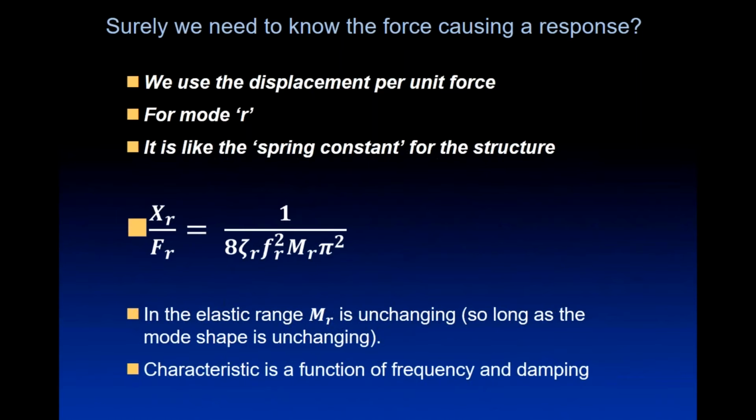Next question, though, is what about damping? Now we've got to go away from this viscous damping model, use our equivalent viscous model, and then look at what that predicts for us. And there we've made an enormous breakthrough. Not only we have, but that's been repeated in Japan, and the Japanese are so keen on it that they've actually incorporated this into their code of practice by the AIJ, Architectural Institute of Japan, and the commentary on their codes tells you what to expect for damping values.